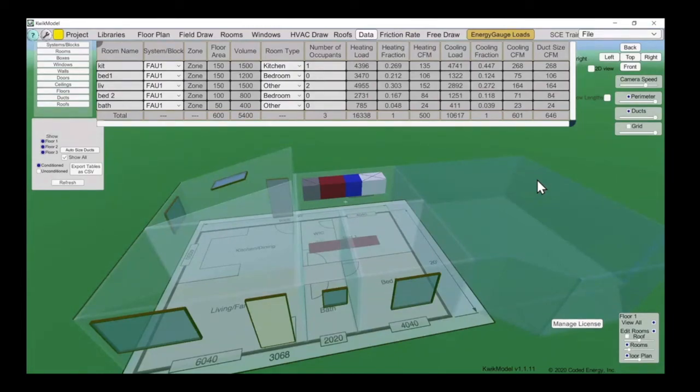And the rate at which we lose money, how much we have, is our budget, okay? And our budget is going to depend on how big or how small the duct is. And if we want to have money left when we get to the end of the duct, we need to make sure that duct is a certain size. And friction rate is the number that describes how much money or static pressure you're losing as you go down the ducts. Okay, that's the best I can do on short notice.